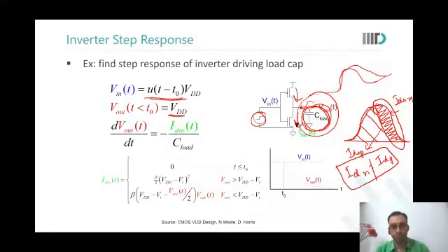Yes, I did. The capacitance was initially charged somewhat, or what? How is that charge left out, which the capacitor is producing afterwards? That I'm not understanding. So I told you, the NMOS will continue to remain in saturation region for a longer duration of time. And only when the capacitance discharges, it will go into linear region. So then its current would discharge. Sir, I have a doubt.